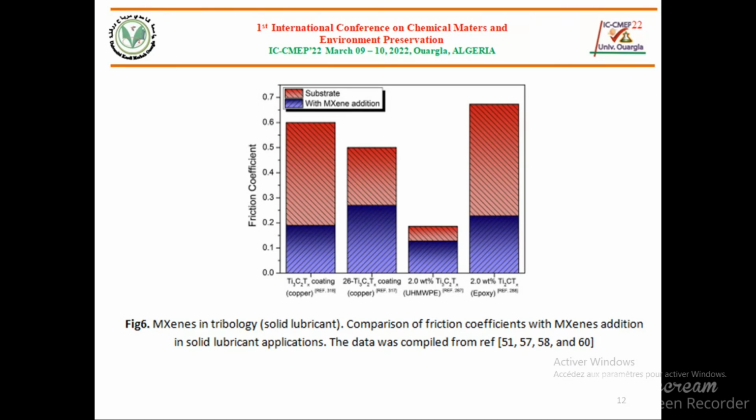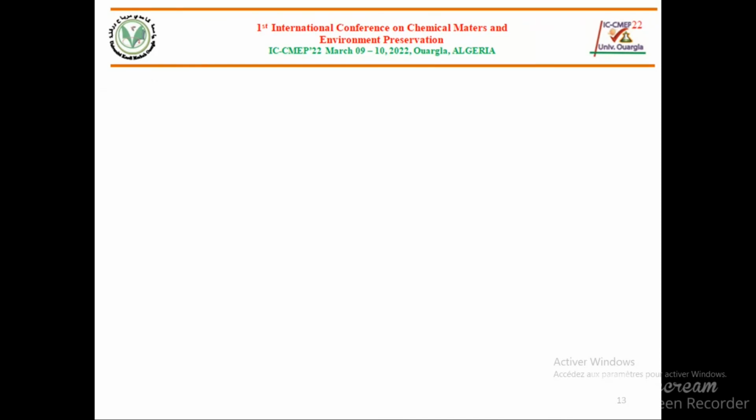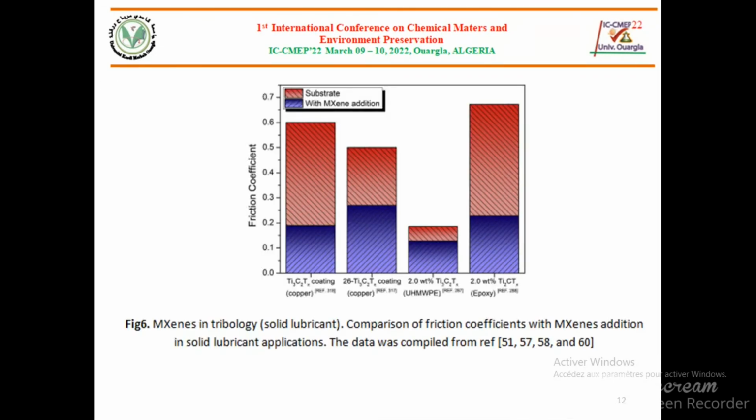The enhancement of wear resistance and COF reduction was attributed respectively to improvements of the composite mechanical properties, which results in better plowing and scratching resistance, and also the tribofilm formation, which results in lower contact area for plastic deformation between the composite and the counterbody.